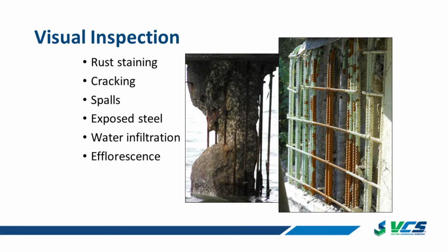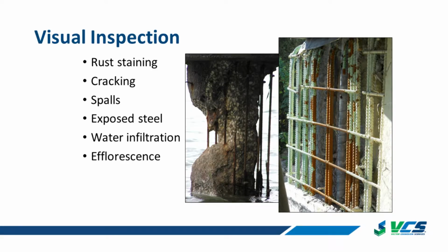Obviously, visual inspection is still important, and I'm an NDT guy as well, like Shane, but we still need to be doing visual inspection. We need to be looking for rust staining, cracking, spalls, where water infiltration is occurring, efflorescence. These are signs of issues. Visual inspection isn't something that's going to go away, and we need to be doing it